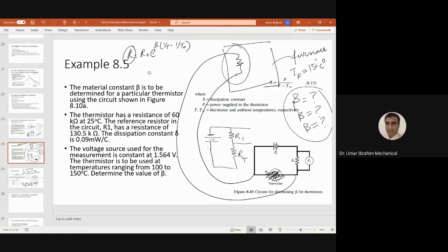Yes sir. Which circuit is this? Sir, that changing... what do you call it, sir, variable resistance. Okay, but we call it a potential divider circuit. Remember the potential divider circuit? Yes, yes. So if I know this voltage and I know this R value and I find out this voltage drop across R1, then I can calculate the RT value, the thermistor value. Is this making sense?